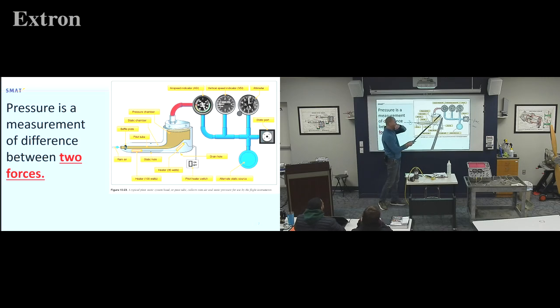The other thing is you don't want to go too crazy high, I say high altitude or low vacuum, without having them even. So when you guys do the Beech jet, what you'll actually do is cap off the pitot one by connecting it to the box. And then you'll open a valve that says, you know what, any pressure on this side will mix with the pressure on that side.